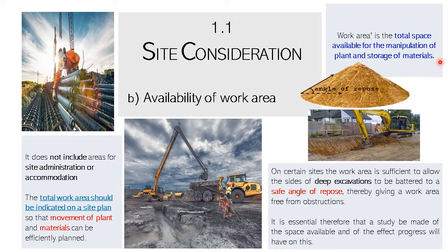The angle of repose is the steepest slope of the unconfined material measured from the horizontal plane on which the material can be heaped without collapsing. This can be seen when a quantity of such material is tipped on a flat surface, it will flow out to form a conical heap. The material within the cone supports itself due to internal friction. The angle of the side of the cone is known as the angle of repose.